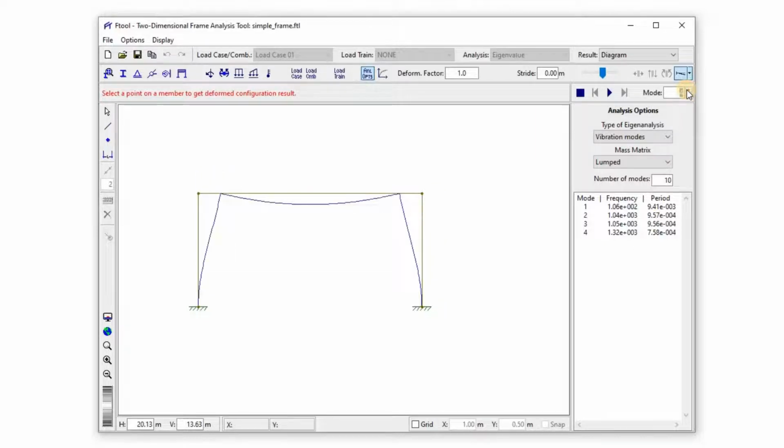as you can see. I should comment that the eigenvalue problem is being solved with the Jacobi method, and it's working well for larger models also. So that was what I wanted to show for the new stability and natural vibration analysis.